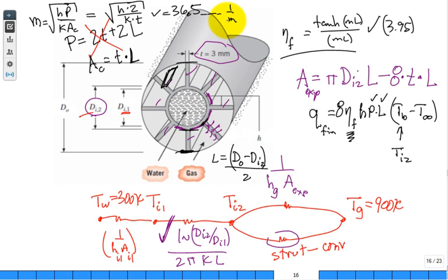And then I multiplied by L. The L is, what is it? I forget my numbers. I have them on the previous slide. But it's like 22.5 millimeter is L for my numbers. And then I get a fin efficiency of 0.82. I'm going to write it right up here. 0.8227, 82%, close to 1.